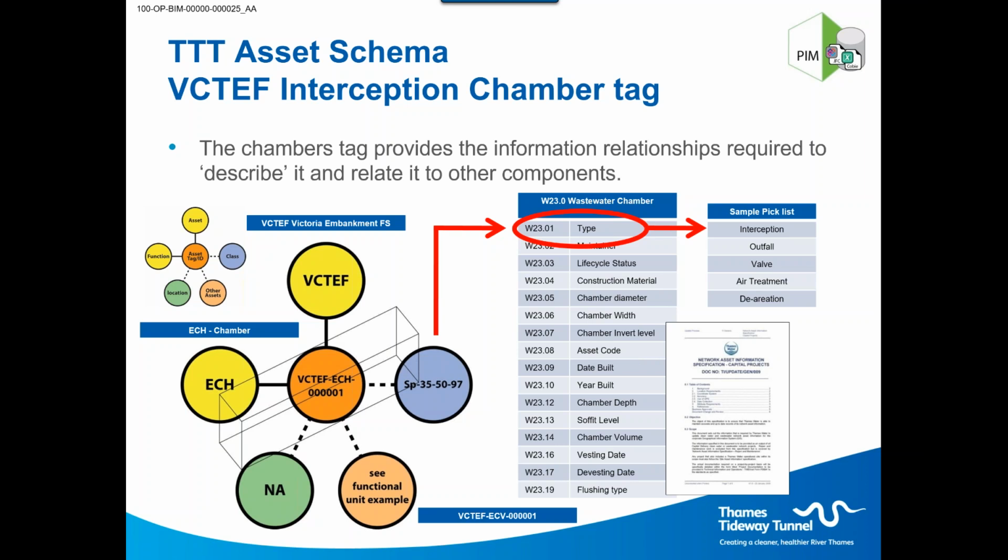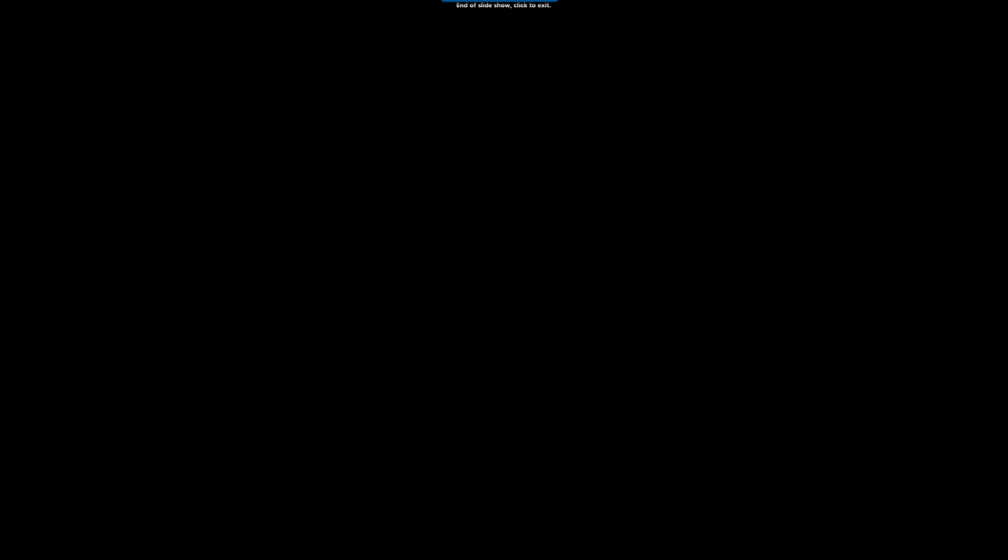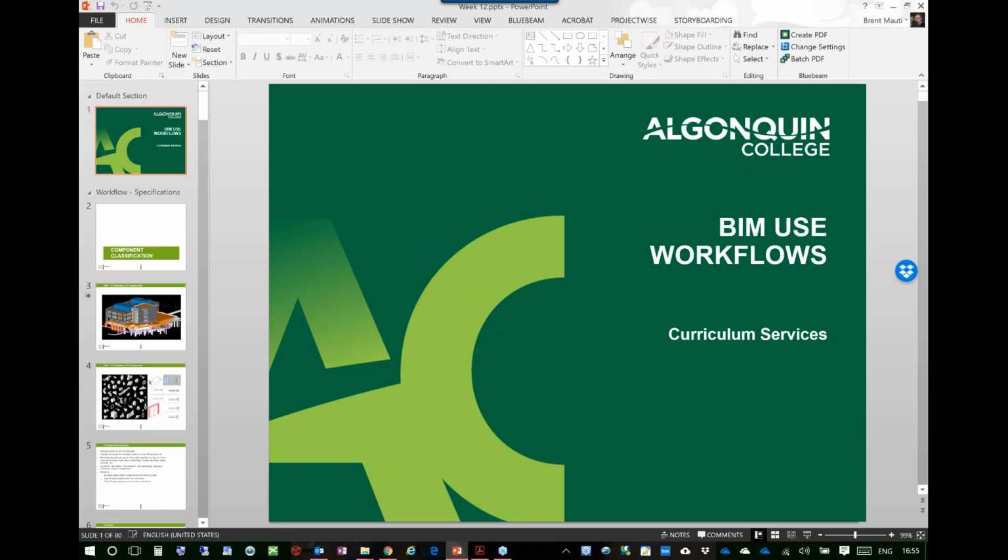I think that's the best way to describe it. Just being cognizant of that fact, right? So as the BIM coordinator, what's your workflow? Your input at the very beginning could be, what's the classification? What's the naming system? Owner, do you care? Do you have an EIR that defines that certain components have to be named a certain way? Yes or no? If the answer is no, life is pretty easy. If the answer is yes, let's just make sure we're accommodating that.